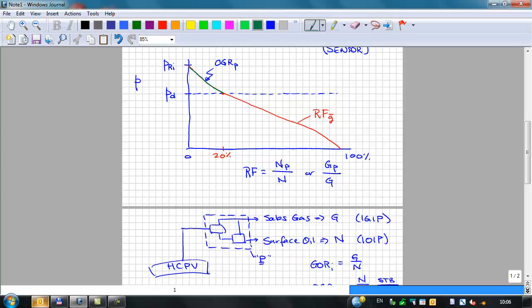At the end of the day, bottom line, whatever oil you recover is being carried in solution in the gas into the wellbore. Now I'm neglecting exactly what the flow phenomena going on around the wellbore are, but essentially that's what's going on. So because of that, your amount of oil that's carried in solution in the gas is dropping. This is going to look like this. Okay?